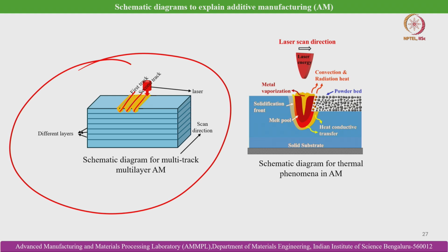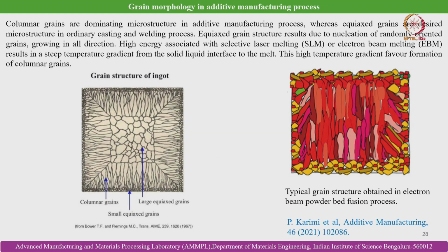Here this schematic speaks about laser powder bed fusion, which we have discussed in detail earlier. So, this is the powder bed which is deposited, and then the laser beam, the energy source, moves over it along a predefined scan path, and it melts and cures the material, and that facilitates microstructure formation in the solidified layer. How it forms, that we will try to discuss.